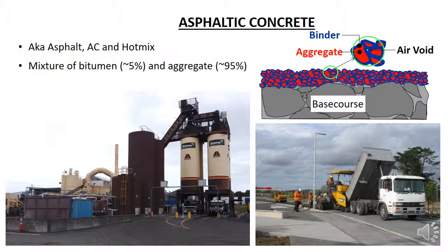The asphaltic concrete is transported to site in covered trucks. At the site, the asphaltic concrete is tipped into a specialist paving machine that distributes it evenly across the road width, as shown in the photo to the right. It is then compacted using steel rollers.